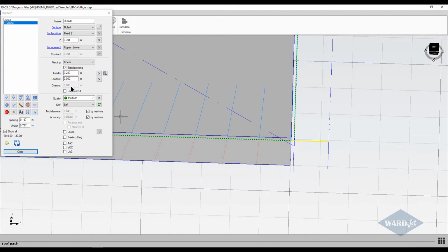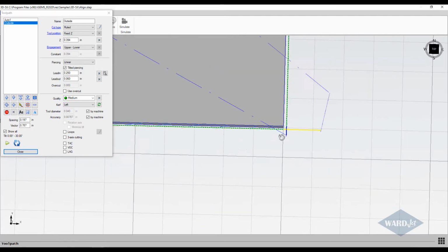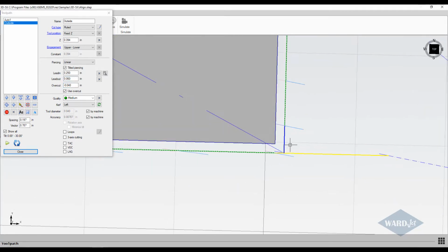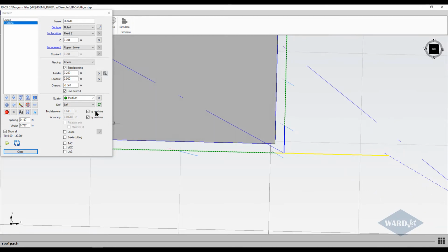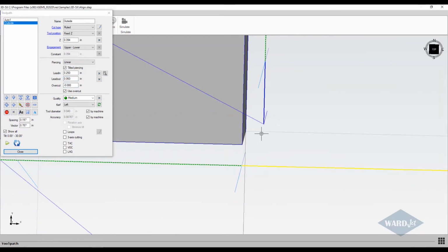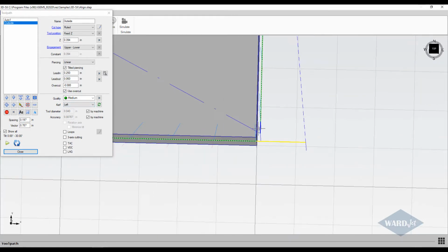So in our lead in lead out area, we have this choice here to use overcut, and if you put a negative number into the overcut box, then it will leave a tab. So right now we've got the lead out but no overcuts, so we tell it to use overcut and then put a negative number in here, like let's try 40 thou, which will have to make it a little bit shorter because now we'd basically be stopping right there where we let in, so we'll make this 80 thou. So with the stream diameter being about 40 thou, we'd probably be left with a small amount of material there, so that's how you can specify if you want to leave a tab on a part.